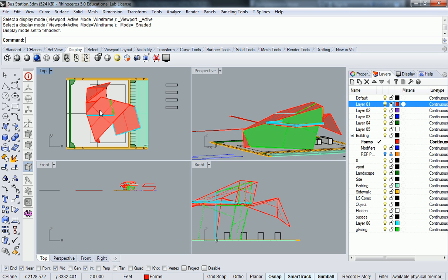And we're going to use Make2D in such a way that it gives us a couple of different sets of information. Maybe we'll just do the overall. So basically, when we use Make2D, we're just going to use the object lines so that we don't see the information that lives beneath the roof of our building.